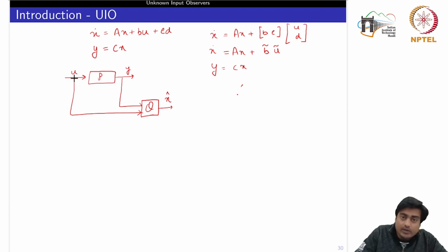So now instead of giving only this u, I have to supply this u tilde if I want to design an observer for this system, right? So I would change here to u tilde, and y would remain as it is, and this would give me the estimate of the state x. Now you would notice that in this u tilde we have two input variables. One is what we have been using so far, the control input u, and d, which is an external disturbance. So if I want to design an observer which can give me the estimate of the state x, then I also need to supply the information of the disturbance to my observer.